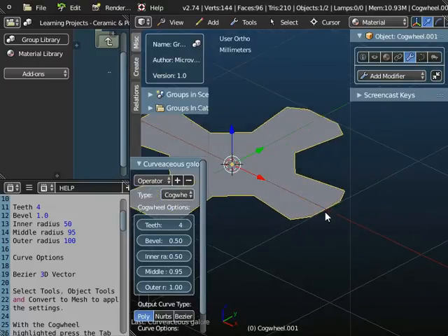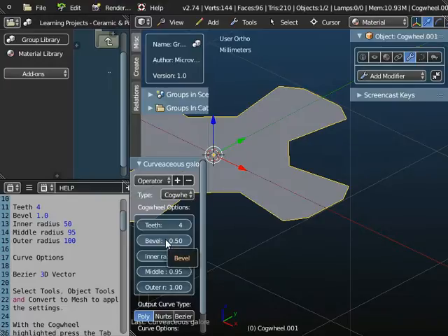That's pretty straightforward. The next thing we're going to change is the bevel. Now this line here constitutes the bevel on the object. If we set this bevel value back to 0, you'll see we've got a very square tooth. If we set it up to 1, the bevel now, this is the bevel. What it means is we've moved from here 0 to the center line of 1. In other words, 1 means a complete bevel, because this bevel meets the bevel on the other side.